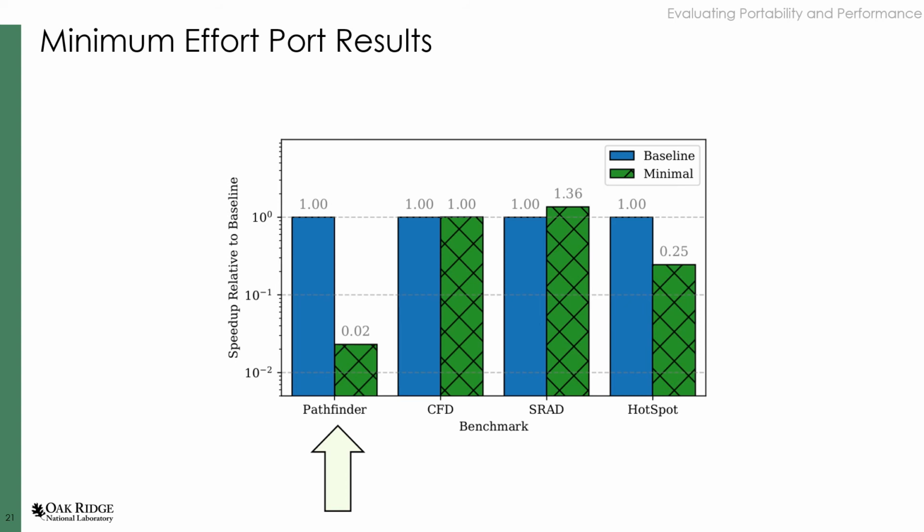This means that one iteration of the kernel cannot be launched until the previous iteration has finished, which degrades performance significantly. Ideally, an iteration of the kernel loop can be launched every cycle, such that an iteration of the loop can be executed every cycle.